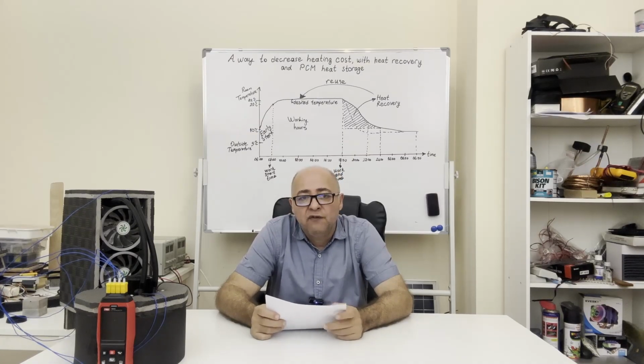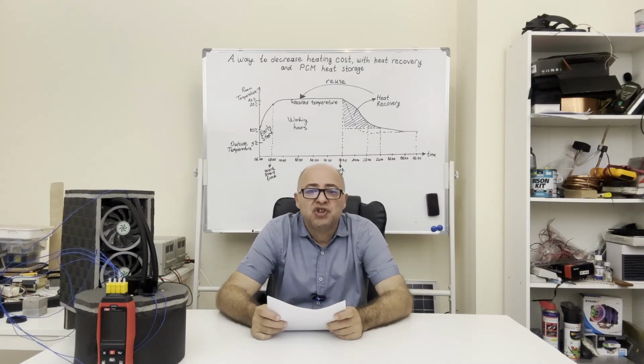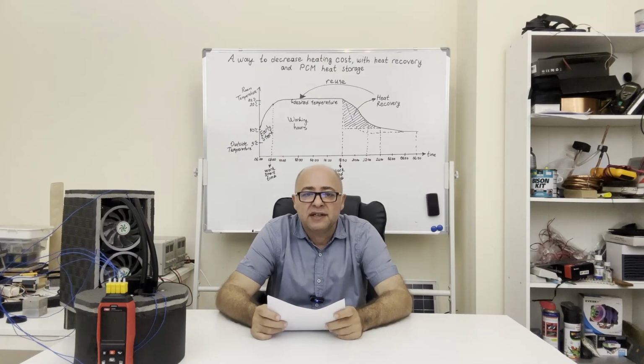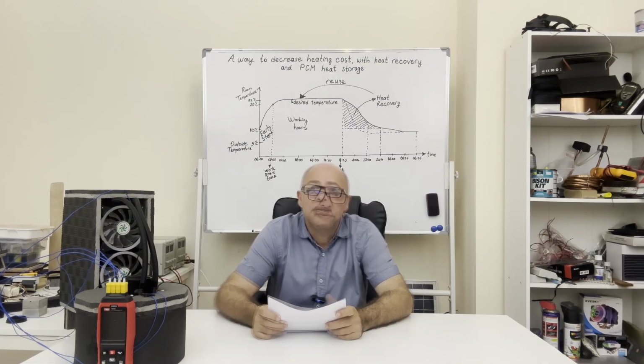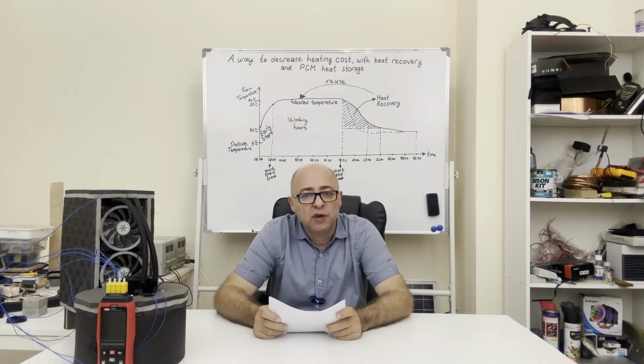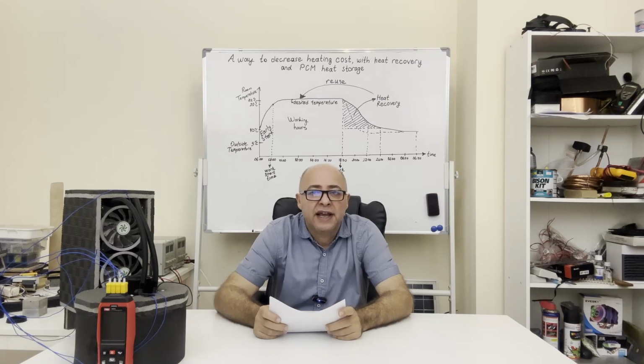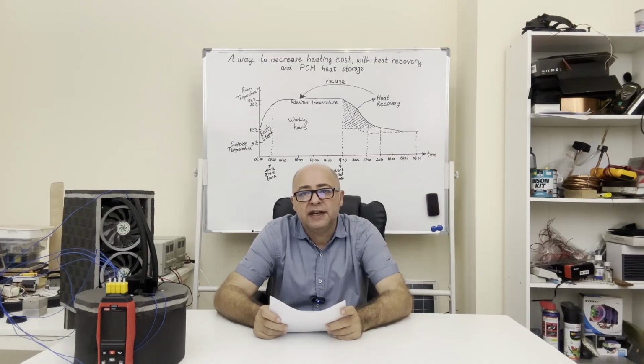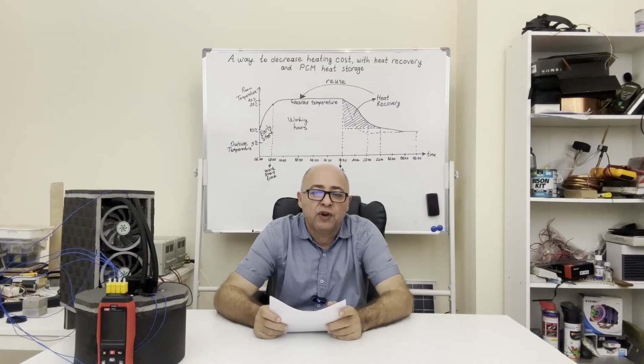Here, I will also tell you about phase change materials, which are the subject of this project. Phase change materials are what we call PCM for short. A phase change material is a substance that absorbs sufficient energy at phase transition to provide useful heat or cooling. In this project, we will use water as PCM. The latent heat of fusion value of water is 80 calories per gram. In other words, it exchanges 80 calories per gram of heat while freezing or melting.